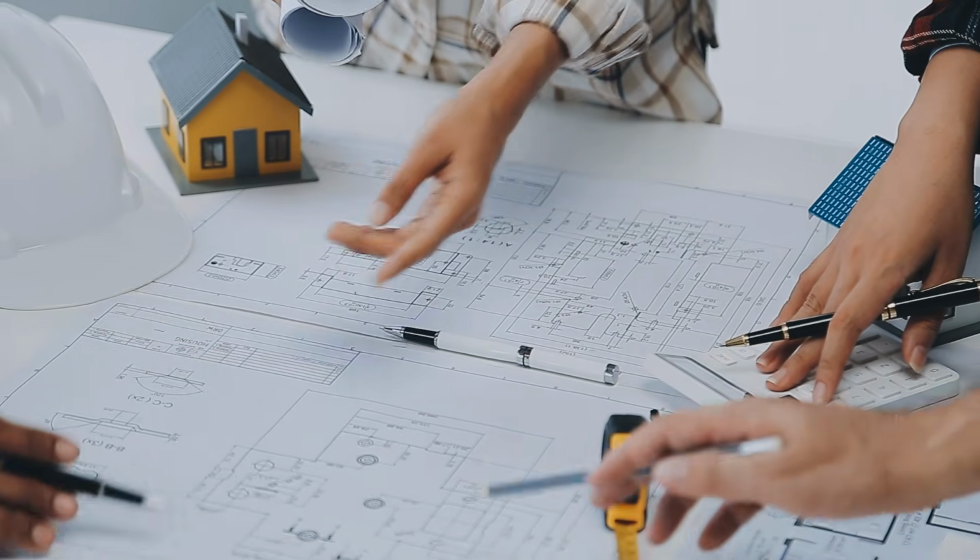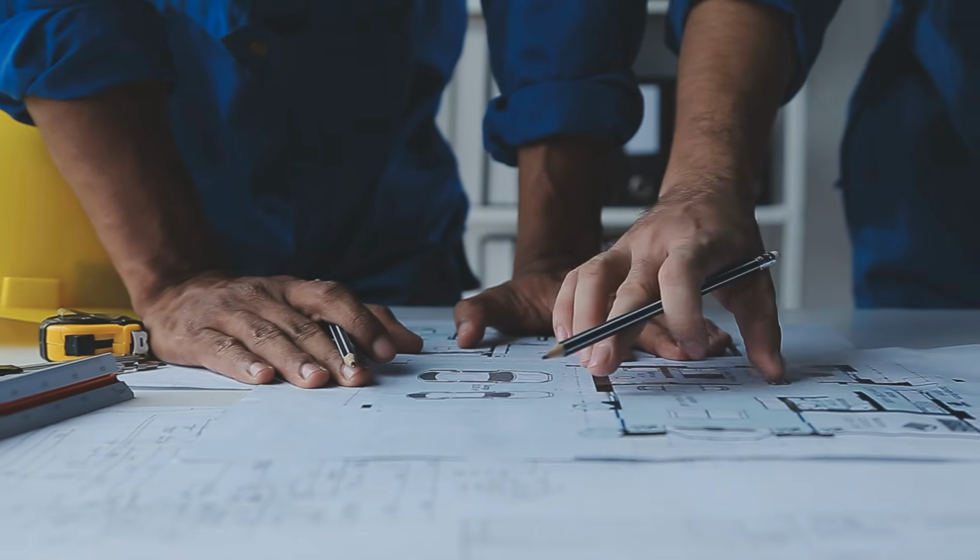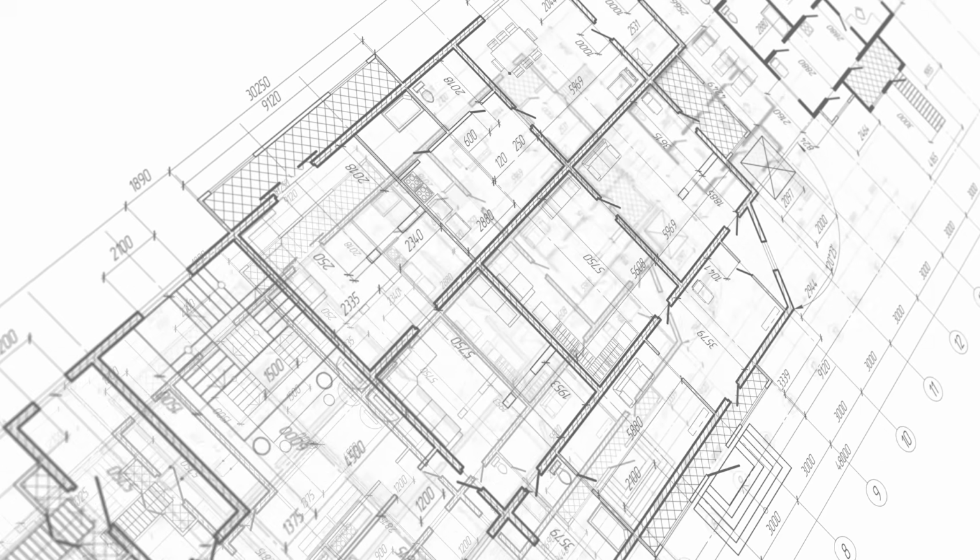As the design progresses from concept design through to issue for construction, we'll have much more detailed drawings and schematics, and our quantity takeoffs will be a reflection of this. And then actually through construction, for every design change, every change to the drawings, we'll have to revalidate our quantity takeoffs and then determine whether we need to do variations.